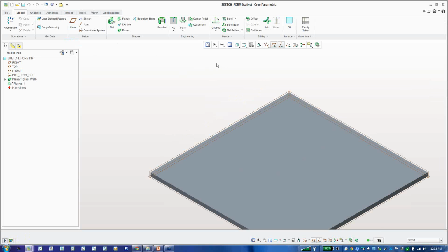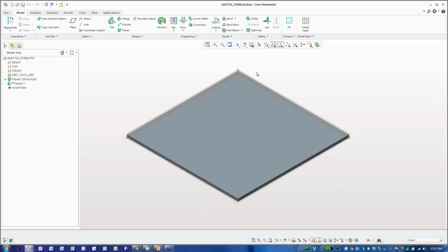Okay, so here's probably one of the really nice things that I like about the new forms tools. So we've always had this punch form where you brought in a part that had basically the positive impression of what you would want to leave behind. So maybe like, I don't know, a louver or something like that.